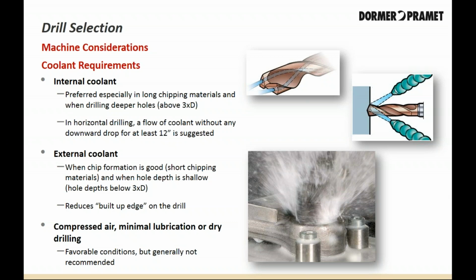Water-soluble coolant is most common and easiest to work with. These coolants work best at speeds above 100 SFM. Oil-based coolants will provide the best possible tool life, but these are best applied at speeds below 130 SFM.